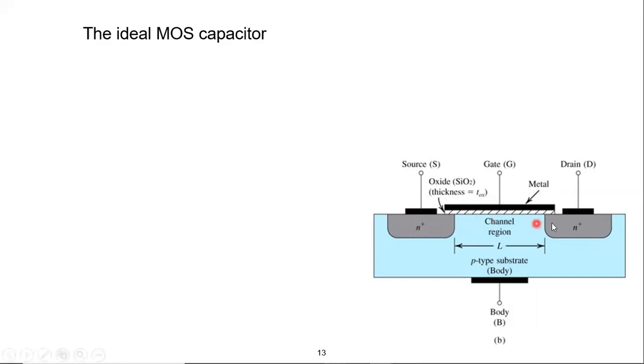Actually, what we studied in part 1, which is NBN, is another form of a semiconductor junction. In the next chapter, we will study the bipolar junction transistor, which is also a semiconductor junction. In the previous chapter, chapter number 4, we studied what we call the metal semiconductor junction, either in a Schottky diode format or in an ohmic format. Now, we will study a third type, which is a metal oxide semiconductor junction. Let's first try to understand how we should construct a metal oxide semiconductor junction.